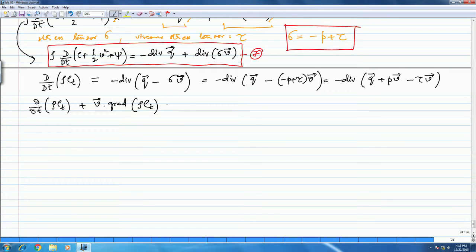rho Et, that is equal to divergence. So I'm going to just write that down. Now, I'm not expanding this part. I hope you kind of get it. If you don't realize how I got this, just drop me a note and I will explain that. Okay. So now what I'm going to do is, this v dot the grad. So if I write it like this, this term I can write as nothing but divergence of rho Et v. I can write it like this.